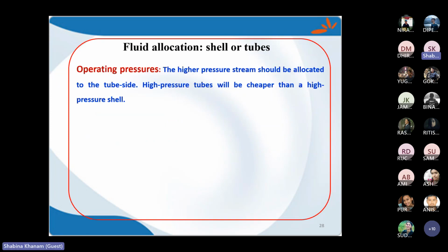Another parameter is the operating pressure. If there is high pressure, it should be allocated to the tube side. For high pressure, we consider more wall thickness, and that thickness depends on temperature and also on diameter.